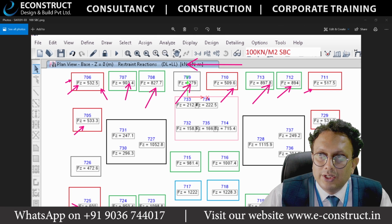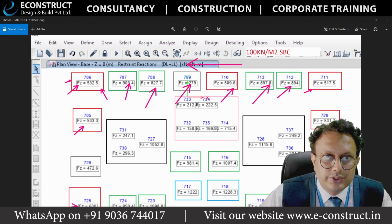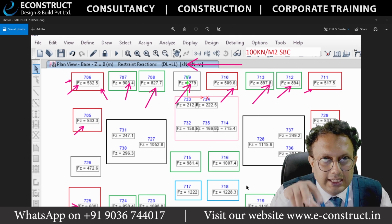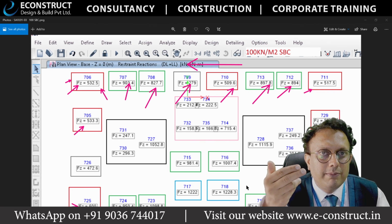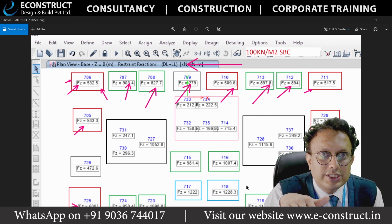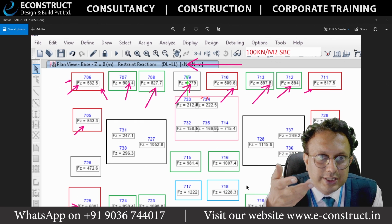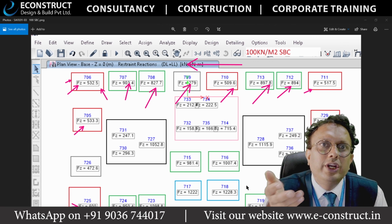Okay. So what you need to do is make sure that you will be dealing with different groups. Initially, take the dead load plus live load, alright, and if you want to do that in the Excel sheet which we have given, you need to add some 5 to 10 percent extra load, because the foundation self-weight will not be there. Understood? So you add 10 percent, 1.1 times the dead load plus live load. But if you are directly doing it in SAFE, you don't need to add it.